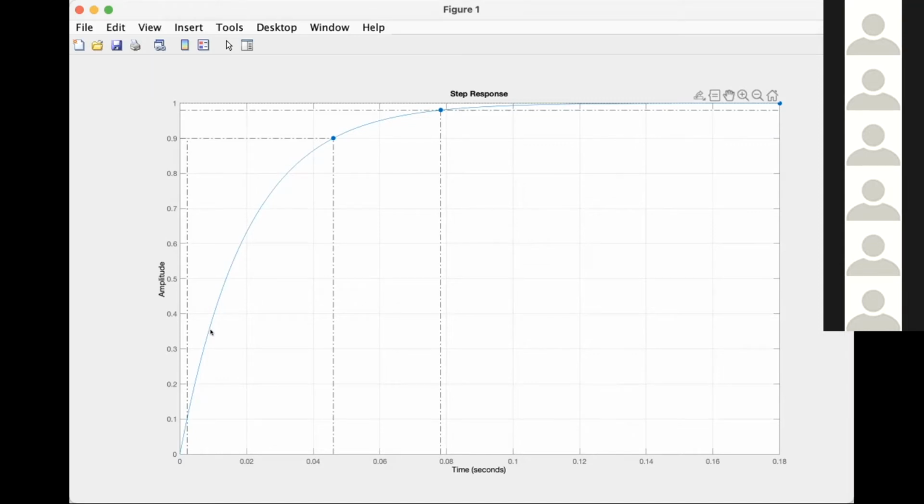So if it's not given, like your assignment, how are you going to find it? In the assignment, there is no transfer function, just graph. So we just click here, 63%, then monitor the amplitude 0.63. Can you see amplitude moving? Yes, Prof. 61, 62, 63.